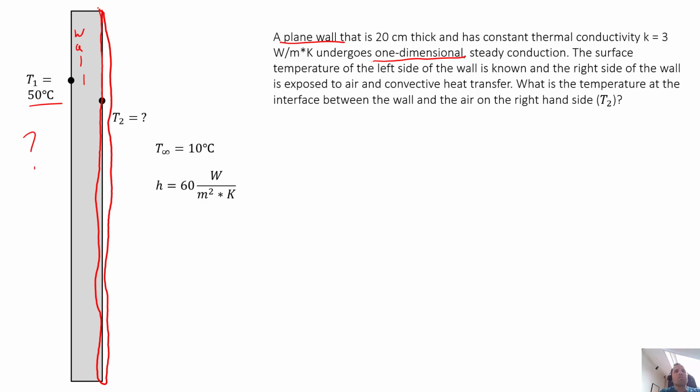So we're going to assume that it has a width and a height, but it has no depth. So it's a two-dimensional shape. So it has no thickness to it and no volume. So let's keep that in mind. So we have our control surface, and if you remember, we want to write out our terms of the energy balance. So we have accumulation, we have in, out, and we have generation. So we just want to carefully think through how to quantify each of these terms.